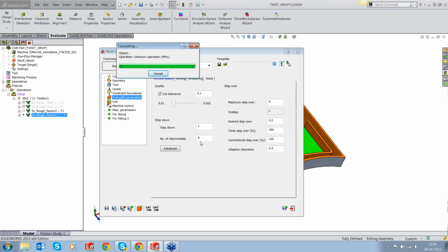So coming back again, how this works. This works in a pretty simple manner. The tool, like I said, always remains normal to the floor surface and then cuts the wall in the direction of normal vector to the floor surface. So if your floor surfaces have an angle more than what the normal indicates, then probably it will leave some material. It doesn't eat into the walls, but it will leave some material. And then you can use the swarfing operation to finish off these walls.